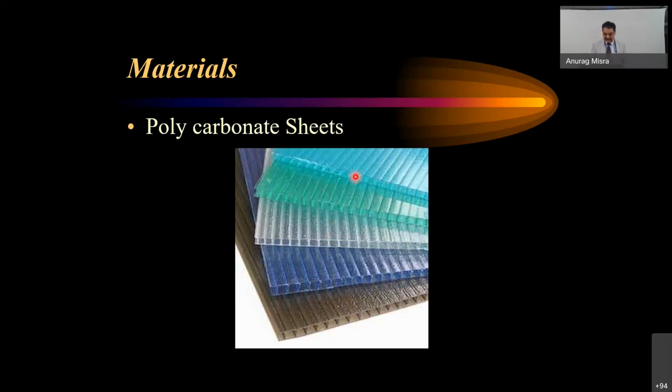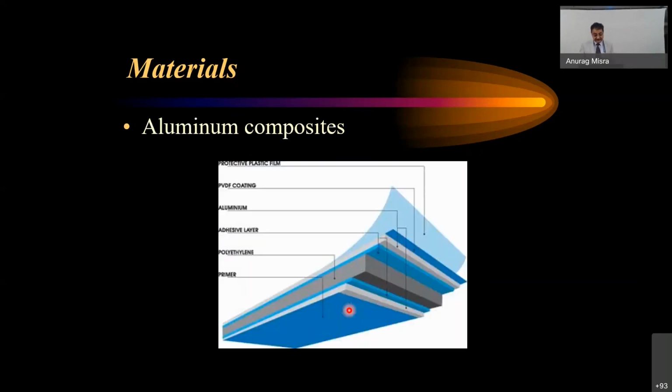So depending on the aesthetics and the imaginations of the architects, you could use different colors, because quite a lot of flexibility is available now. And also what is the size of the covering, the span where you want to leave. Normally for the sheeting we are using 1.2 to 1.4 meter spacing of the purlins. The polycarbonate with this arrangement, making it double layer, you are able to match those spacings as well.